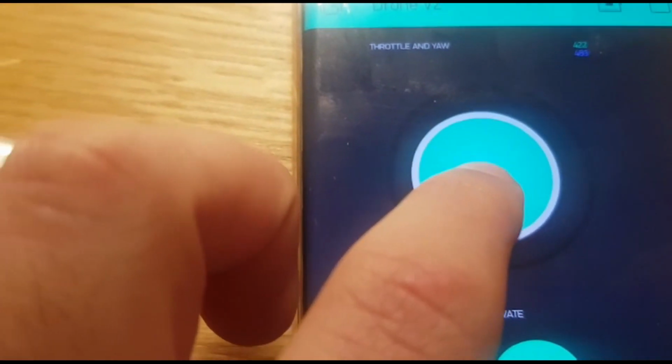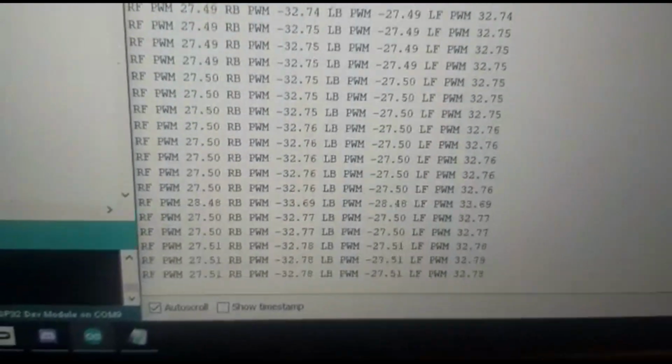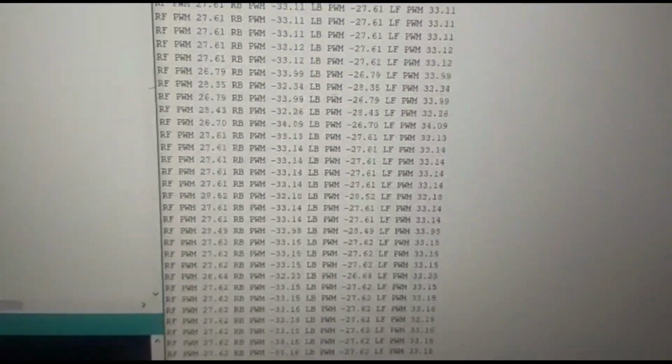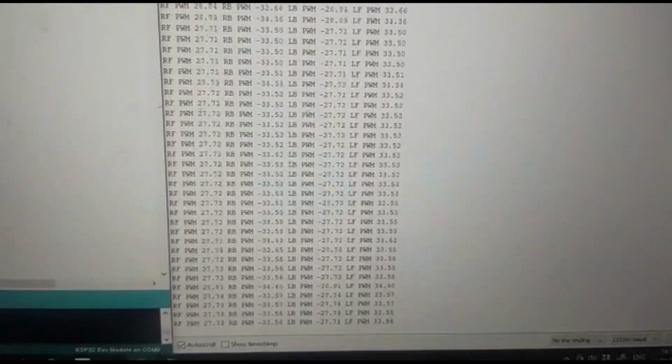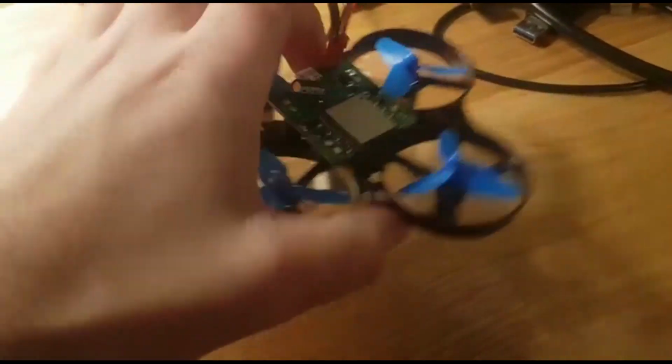Now we can just make it a bit low again, 0. I'm still seeing some negative numbers, so I do use the absolute number because I can't send a negative number to a PWM signal. But now what we have to do is play with the PID values with the drone. So I've got it here, and then I have to see when it starts stabilizing. So that's the next step. So that is the breakdown of the code.